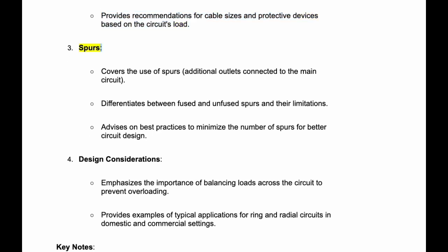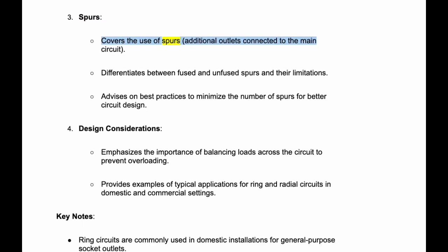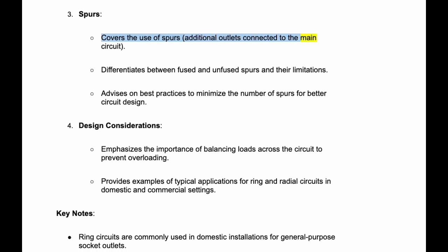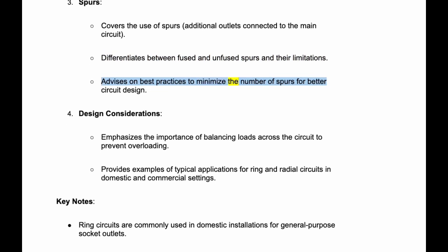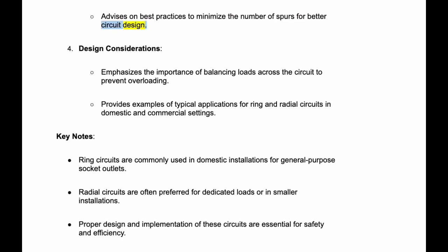Spurs. Covers the use of spurs, additional outlets connected to the main circuit. Differentiates between fused and unfused spurs and their limitations. Advises on best practices to minimize the number of spurs for better circuit design.